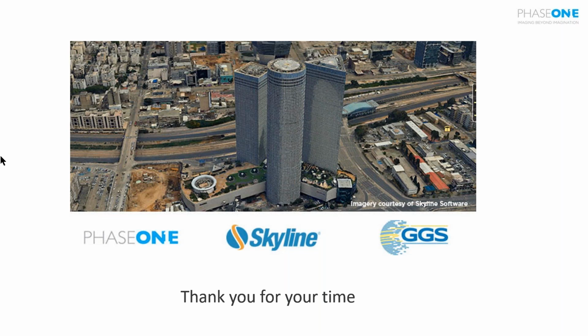How critical is the quality of the aerial triangulation? How many pixels of accuracy is still allowed for a good instrument model? The aerial triangulation is the most critical part of the quality of the mesh. We usually achieve sub-pixel accuracy correlation between all of the cameras. The two projects I showed were around 1/3 of a pixel. It could get down to 1/4 of a pixel.